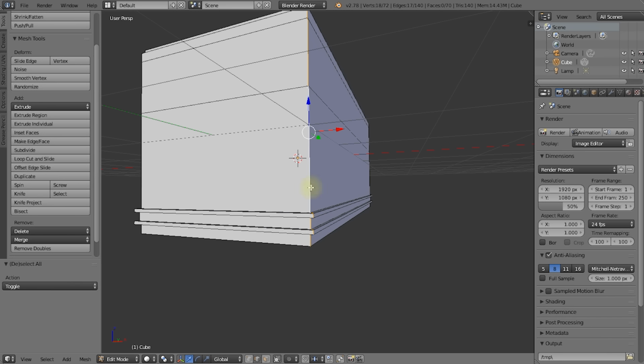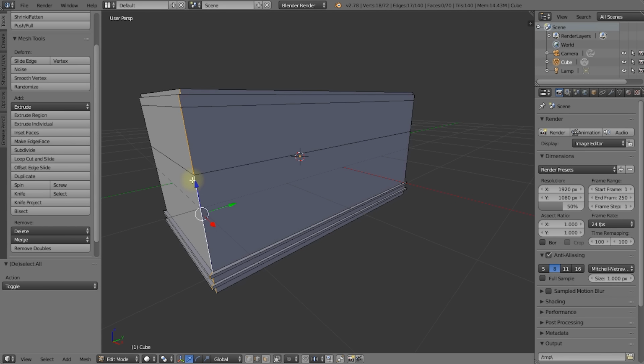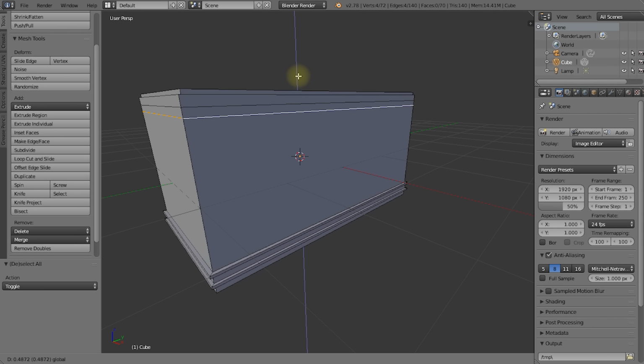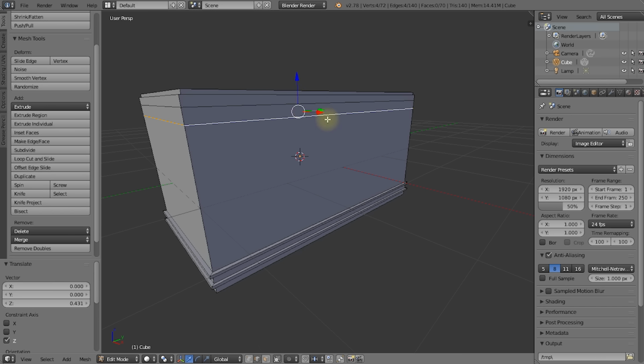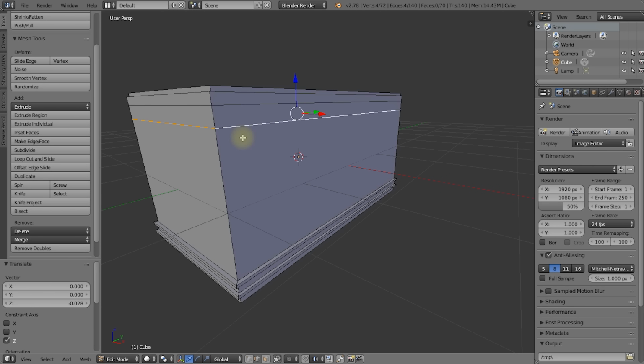The selection will essentially try to follow the edges along a straight line, and this makes it a whole lot easier. Now, to move the edge that we just added, again, hold down Alt and right click on it to select it all around the box. And it's way too low, so just grab this and drag this up to about there. So we're just defining the upper detailing rim that we want to add. And let's return to face selection mode. And you will see me use different options. Sometimes I use the shortcut keys, sometimes the menu options.